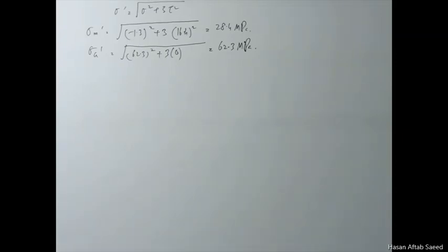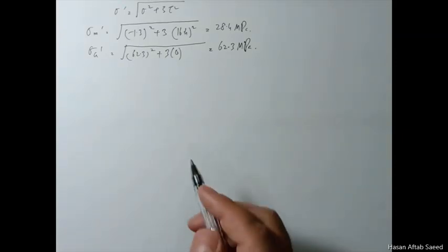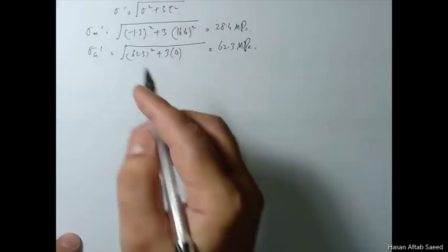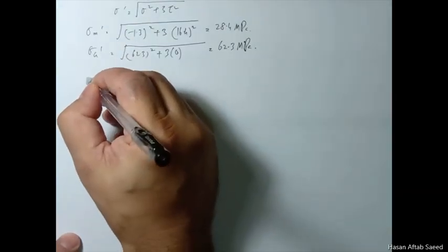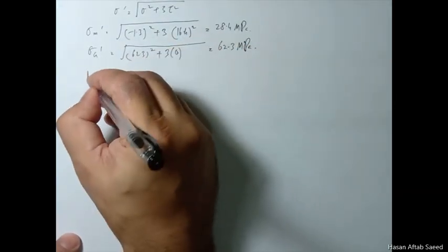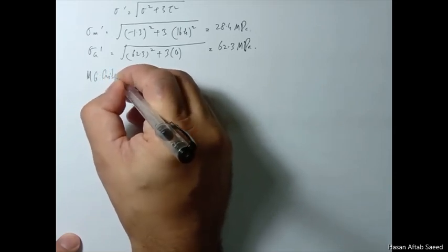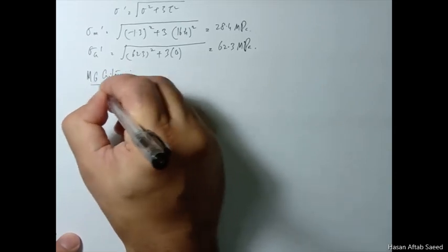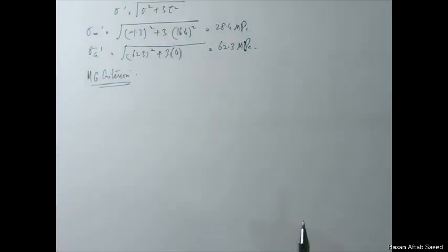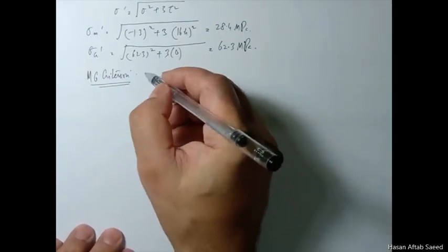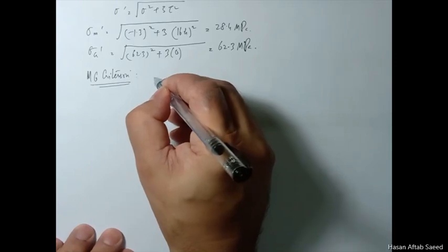And if we have these values, then it's simply a matter of applying the fatigue criterion. Let's apply the modified Goodman criterion. We were not told to apply a particular criterion, so it's our choice. The simplest one is this one. You can equally apply Gerber.